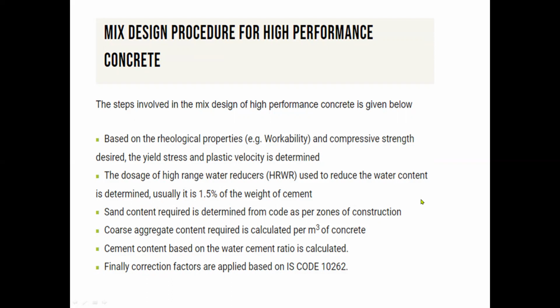Sand content required is determined from the code as per zones of construction. Coarse aggregate content required is calculated per cubic meter of concrete. Cement content based on the water cement ratio is calculated. Finally, correction factors are applied based on IS code 10262.